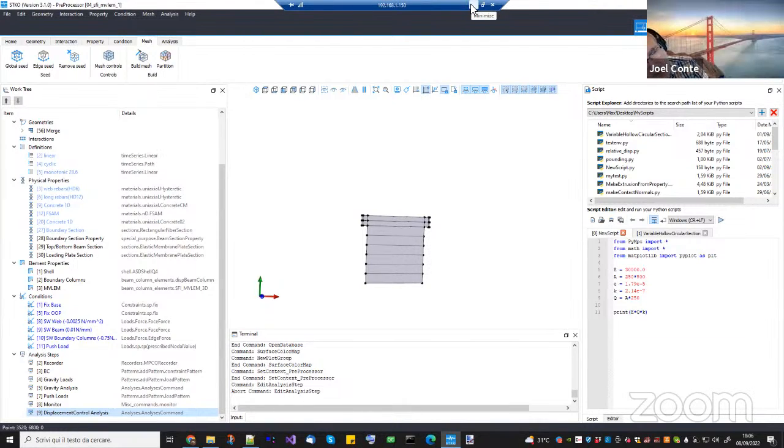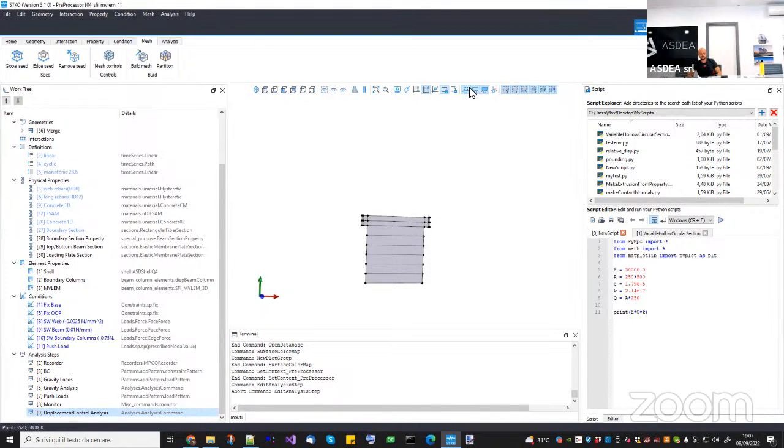Sure, because arc length, like you said, right? If you have an equilibrium branch that comes from, especially like you said, buckling, but even inelastic buckling, you have one very nonlinear branch where you can have snap through and snap back and you can follow it. But now what about if you do cyclic loading, like hysteresis loops? I think with the arc length, when you do the unloading, it could be confused and get the other solution that continues to load, right?